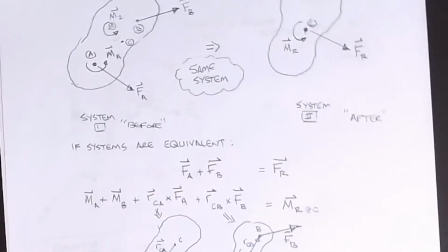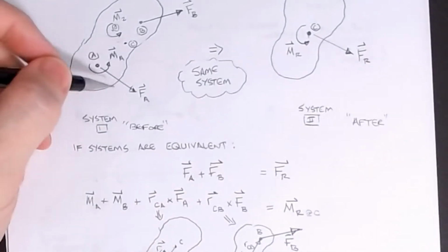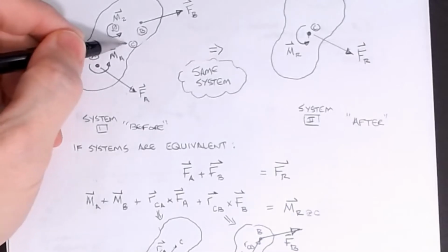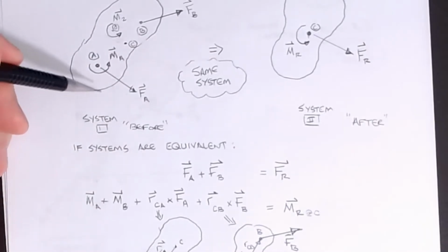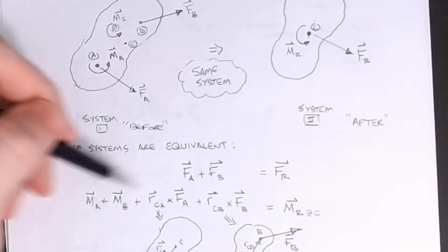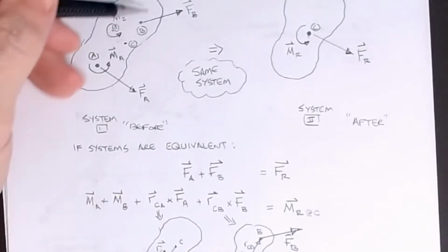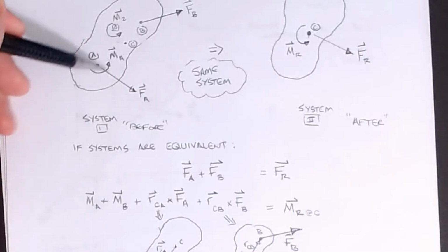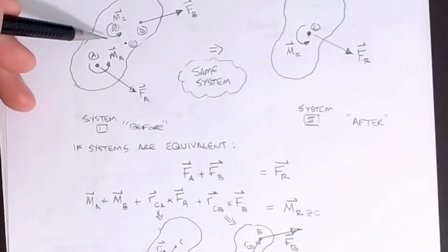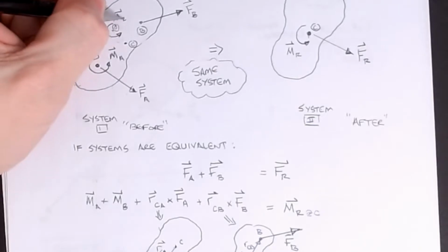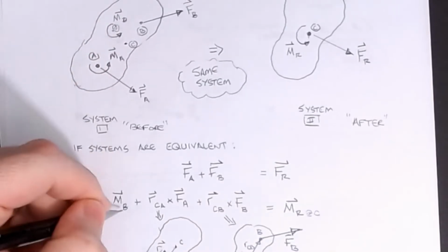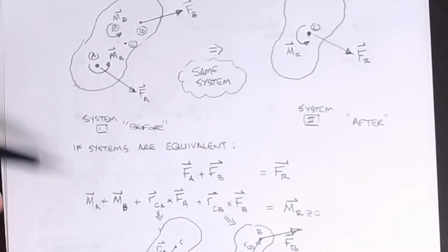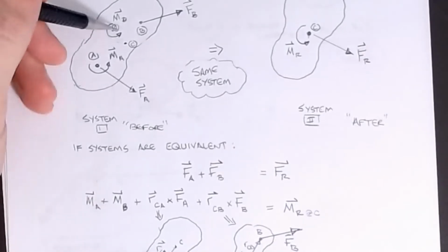Now, let's say that I'm after the equivalent effect at point C. Well, for point C, the same should be true for the moments. And so I would take the sum of moments at C for all of this. Now, we know that moment vectors are free vectors, so those just add straight in. Let's call this MD. And so MA plus MD, that's the two free moments.